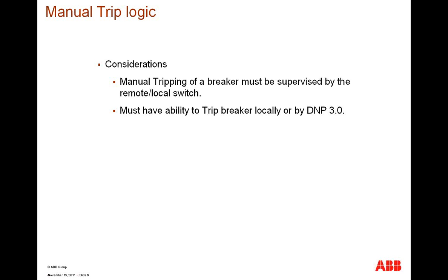So starting with the manual trip logic, for this particular consideration, the manual tripping of the breaker must be supervised by the remote local switch, and it must have the ability to trip the breaker locally by HMI.